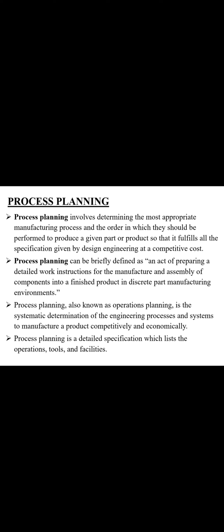Now I am teaching about process planning and cost estimation. What is meant by process planning? It is understood that the product design for each product has been developed in the design department. To convert the product design into a product, a manufacturing plan is required. The activity of developing such a plan is called process planning.